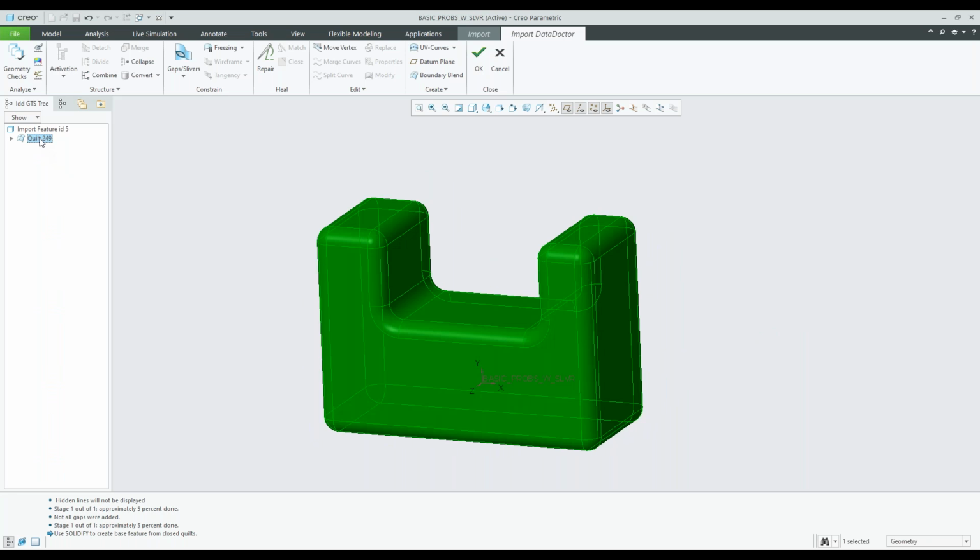So something that's new in Creo 7 as well, you have to tell it you want it to be a solid. Okay, because you're working with multi-body components now, you can have a solid component, import a surface thing, and then you can use that to make cutouts and do various things with that surface model. Okay, so in this case, we want it to be a solid. So we're going to tell Creo, make it a solid body.